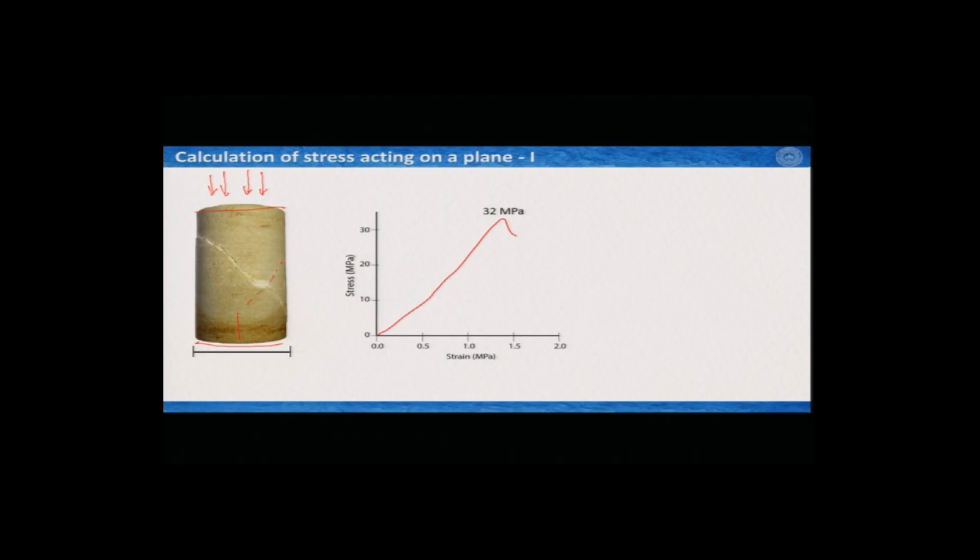And we just learnt the theory of shear stresses, and you can see here very nicely that two surfaces were formed, one is prominent, another is not that much. But now we know that we have applied a load here, say the load was F, and we know the area of the top part of this cylindrical sample. Say for example I know this is 2.54 centimeter, that means it is 1 inch.